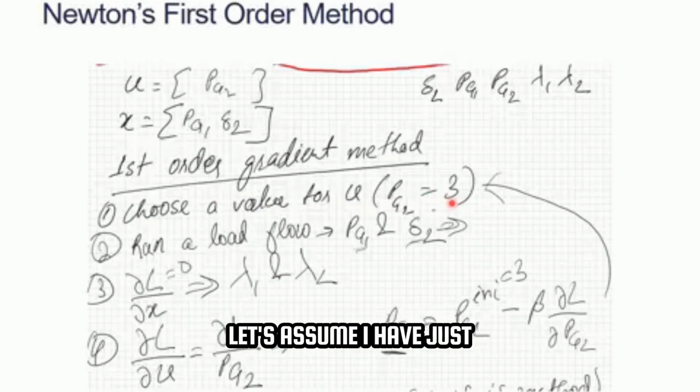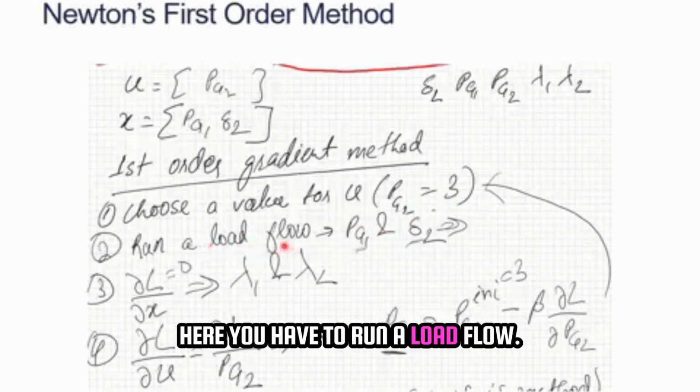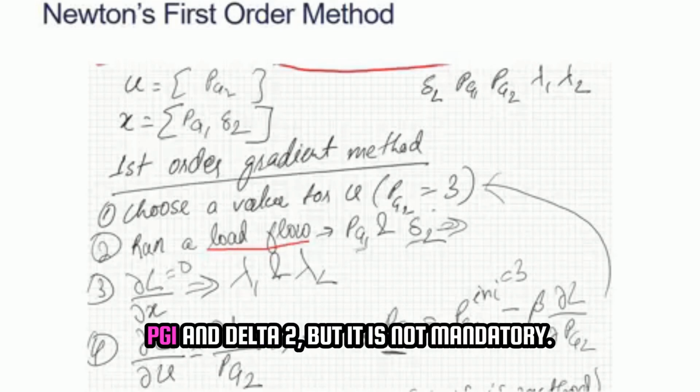Let's assume I have just given a value that PG2 is 3. So how to get this PG1 and delta 2? Here you have to run a load flow. Without running a load flow, you cannot get the values of PG1 and delta 2. But it is not mandatory.